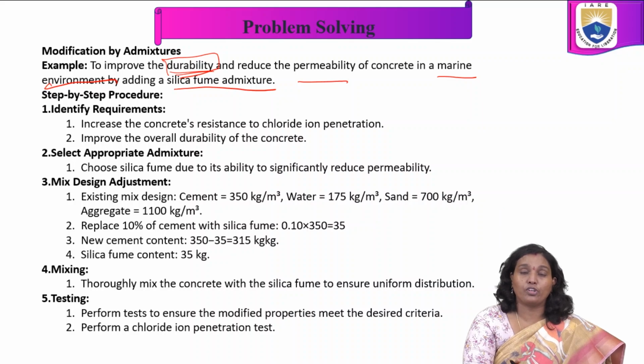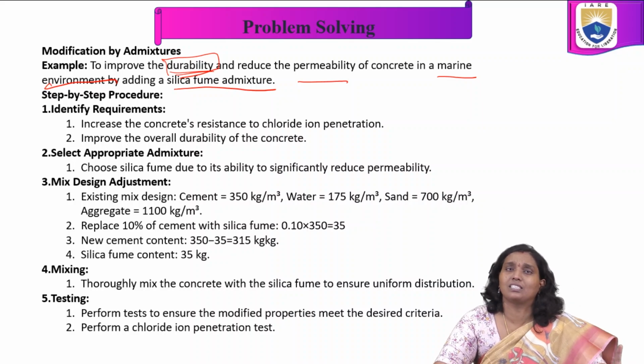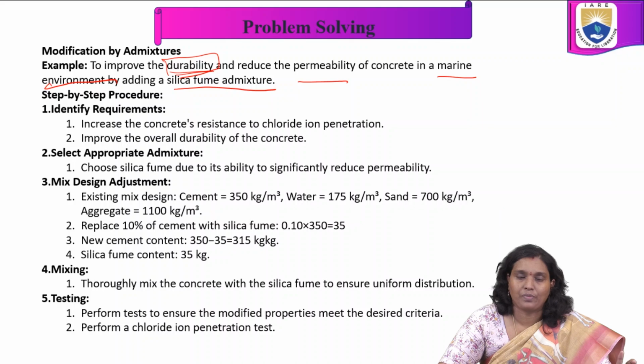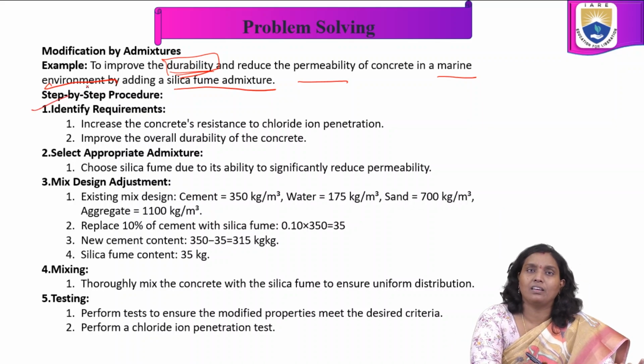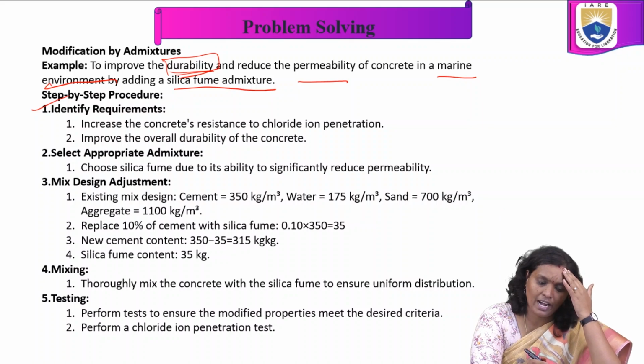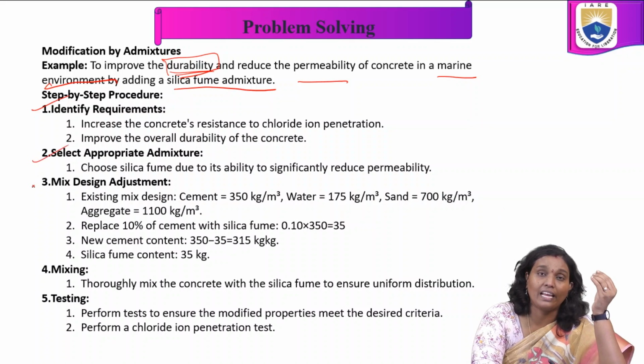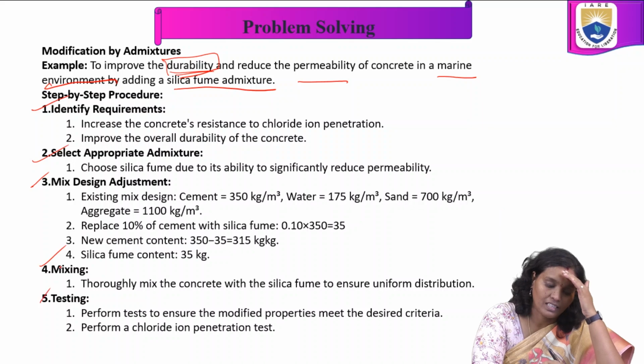For this, identifying the requirements is the primary step. The step-by-step procedure is: identify the requirement, select the appropriate admixture, mix design adjustment, mixing, and testing.